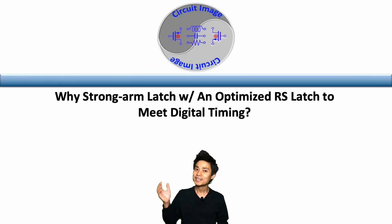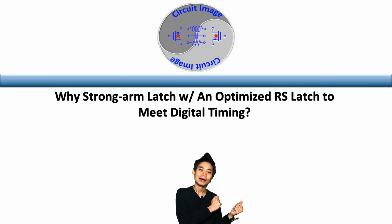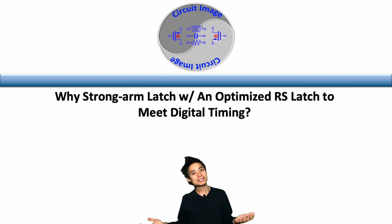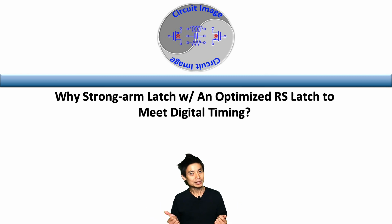We will discuss the StrongARM latch itself and understand it's quite handy owing to its compatibility with the following digital CMOS logic. However, we never discussed how the compatibility could be done. Also, the extra circuitry will limit the following digital timing, and we need to watch out carefully. Therefore, we need to know why the StrongARM latch would need an optimized RS latch to meet the digital timing